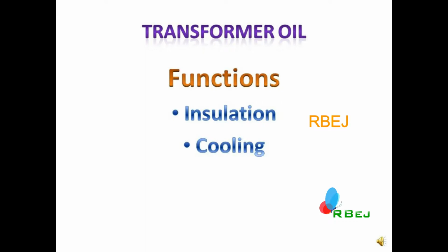5. High flash point. 6. High chemical stability. 7. High electric strength, kV. 8. High volume resistivity. It should be non-toxic, PCB-free (synthetic fluid before 1990). It should be compatible and consistent with transformer construction material. It should be chemically stable and retain its properties for a longer time.